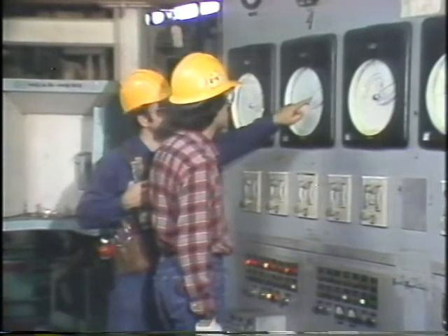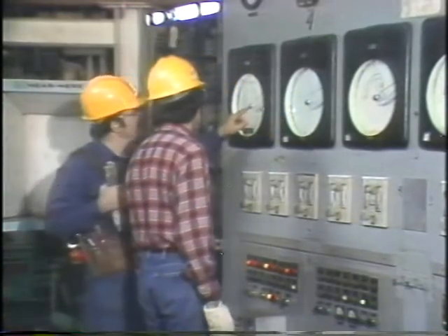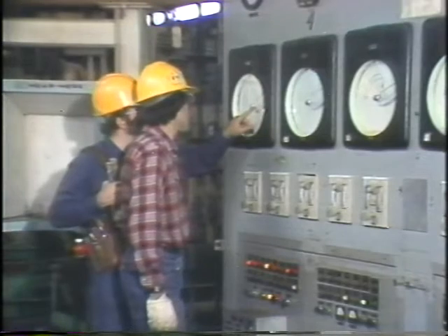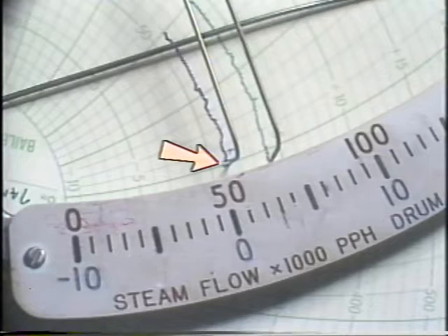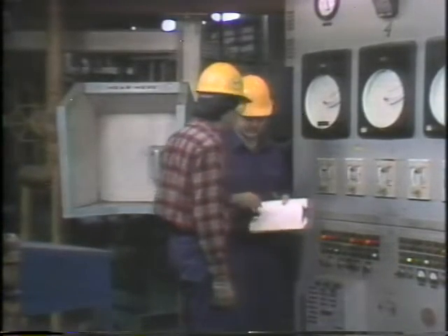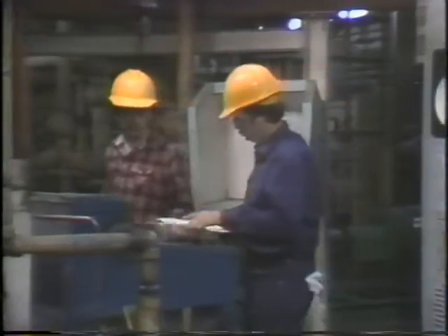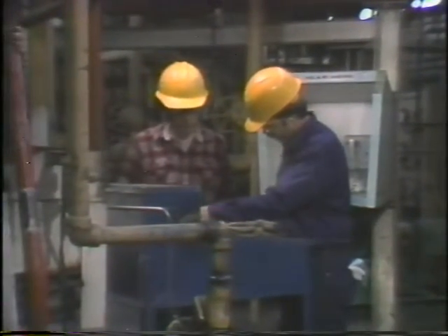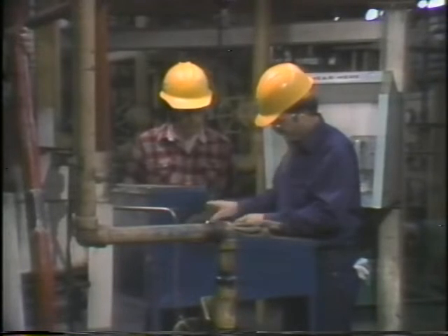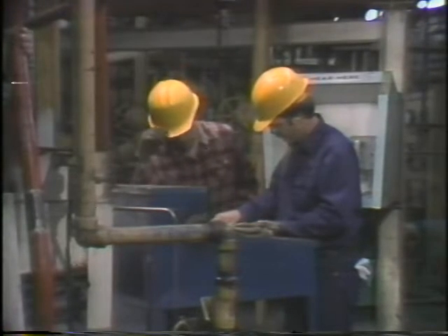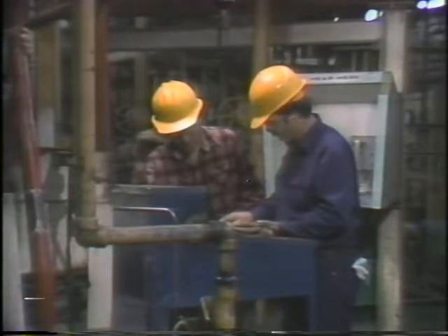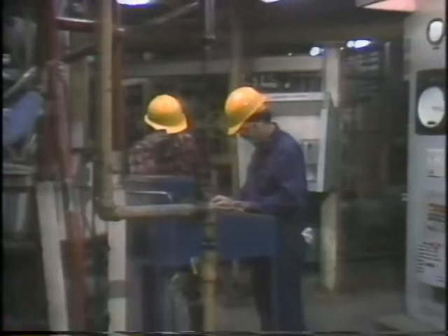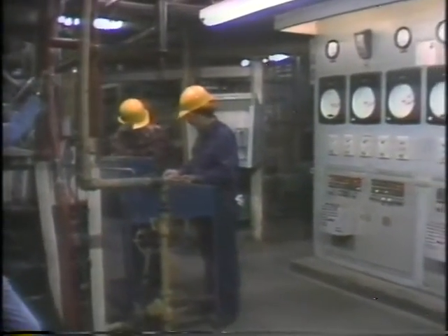But when they looked at the indications, they found out that the system still wasn't working right. The feedwater flow indication was okay, but the drum level hadn't changed at all. It was still high. I tell you what, let's take a look at the diagram. Now, I know that the transmitter's working right because I just calibrated it. So I know that that signal...